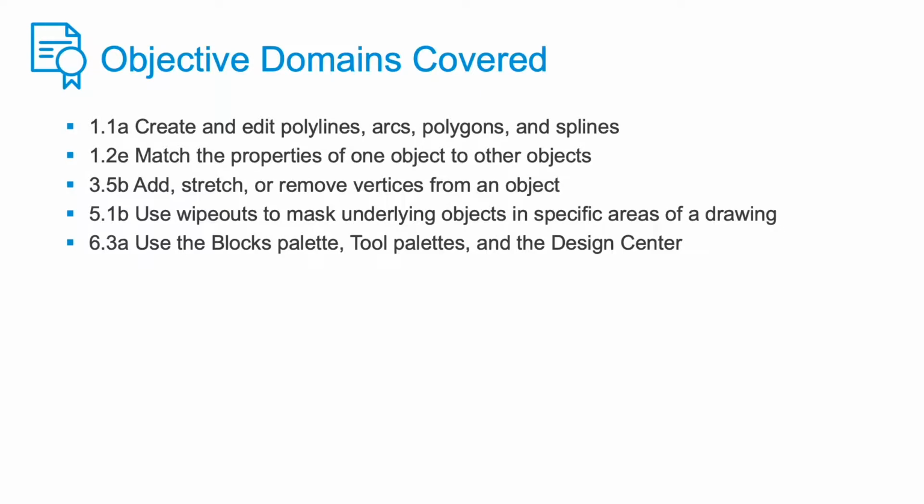In this lesson, we used wipeouts to mask some elements in our drawing to see how changes would appear. The wipeout tool is useful when you want to explore different options without having to delete or modify existing elements in your drawing.